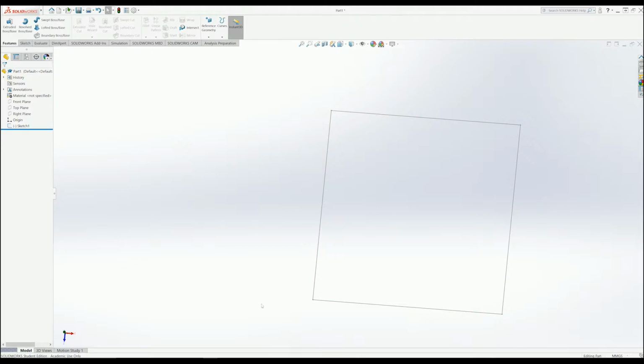So what you want to do is come up to sketch. If you click on it and then press F2 on your keyboard, it then allows you to change the name of that sketch. So I'm going to call this base shape. That is the base shape sketch. It's really useful to rename these parts because as we go through and you end up with very long trees, you want to be able to modify and edit them individually to change the shapes of things.